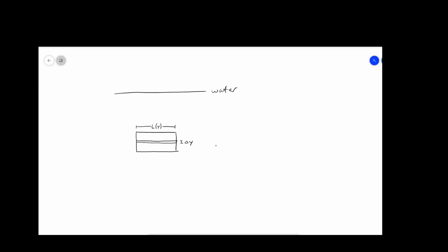So let's think about what is the force being exerted on that strip, right? Well, it's the pressure times the area, right? But the pressure we said was rho times gravity times the depth. So we would have to say, well, what depth is this thing at? And for the purposes of what we're going to do here, I'm going to call the surface of the water y equals 0. And I'm going to say that going down is actually increasing y. Because when we use that letter D for depth, that really kind of means that we're pointing downward for the positive direction. So let's just stick with that convention. It also negates the use of a lot of negative signs.